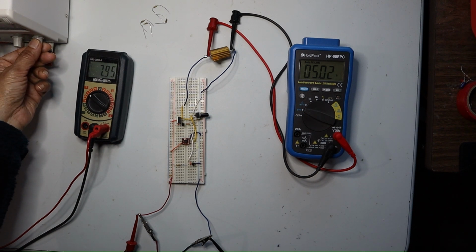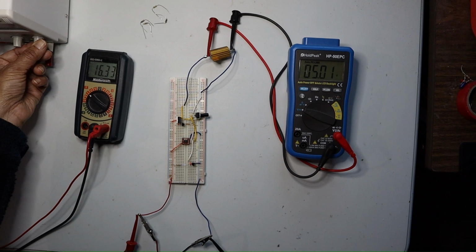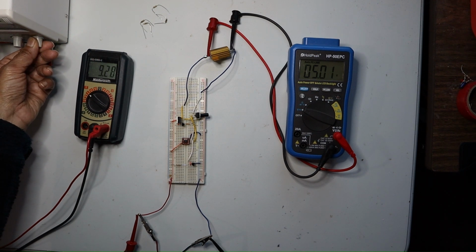Now you can see I am using a different power supply, that is the power supply with an op-amp. With the increasing or decreasing voltage, the output voltage varies very little. You can see now 9.6, 10, 11, 12, and the output voltage remains the same at 5 volt. So it is way more stable than the previous one. That is, the supply with the transistor is less stable compared to the power supply with the op-amp.